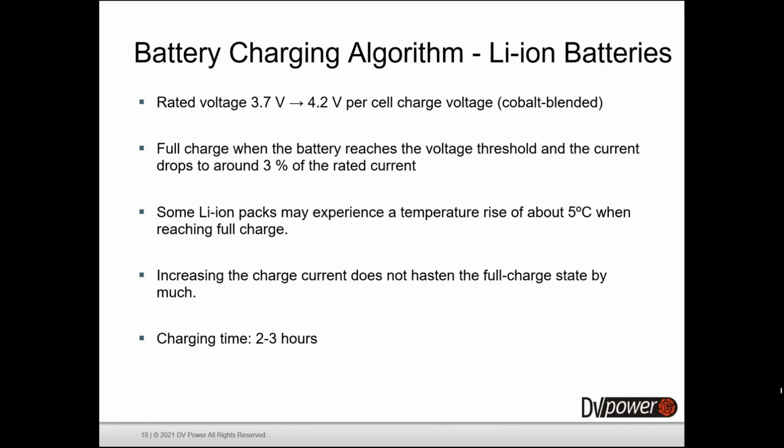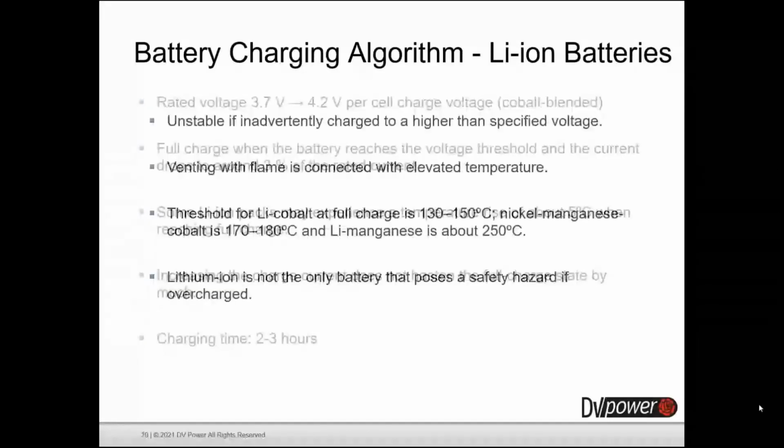And the advised charge rate of an energy cell is between 0.5 C and 1 C. The complete charge time is, as stated here, about 2 to 3 hours. Manufacturers of these cells recommend charging at 0.8 C or less to prolong the battery life. However, most power cells can take a higher charge C rate with a little stress.